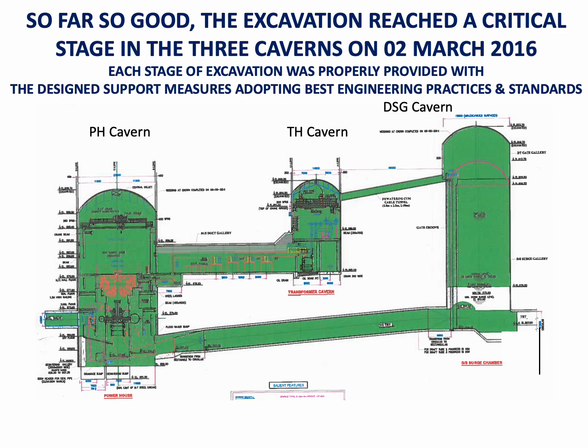The powerhouse cavern had been excavated to its full depth of 52 meter with 6 pressure shafts excavated fully entering through its upstream wall, the 3 huge bus ducts, an emergency tunnel and a connecting tunnel, as well as 6 draft tubes had been fully excavated emerging out from the downstream wall of the powerhouse cavern, thus making the powerhouse cavern structurally most precarious with multiple openings existing in both its upstream and downstream walls.